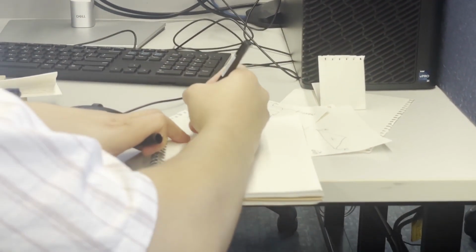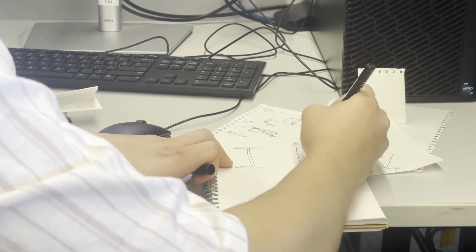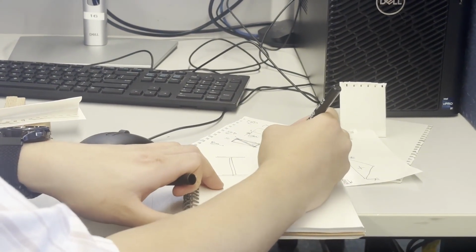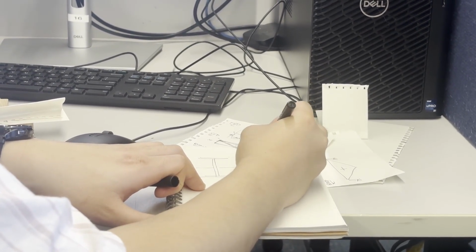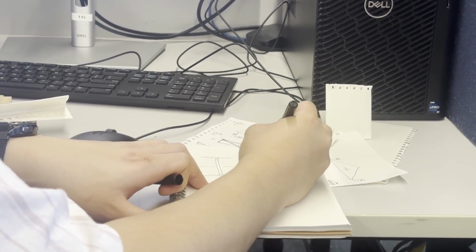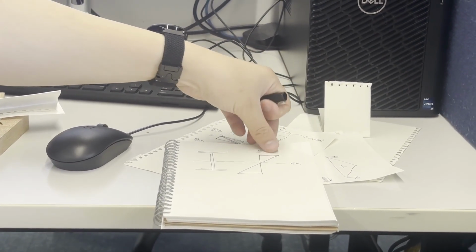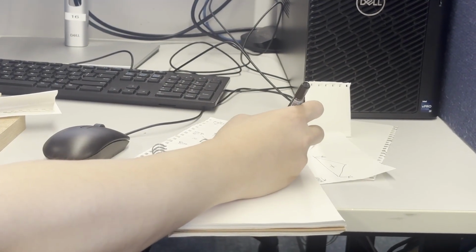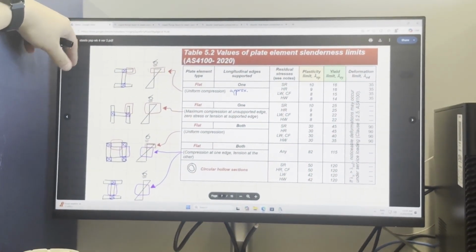If that's our beam, and this is our elastic bending stress, and that's the neutral axis, that's the stress distribution on the flange. It's basically a rectangle because it's so thin. I know it's a trapezoid theoretically, but it's basically taking uniform compression because it's essentially a rectangle. So that's when you would take uniform compression in a top flange, for example.